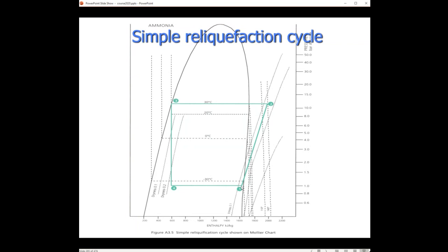Here we take away the vapors, this should be outside of that, because otherwise there is still liquid inside the vapors, and that is not so good for your compressor. So it should be outside this, on the right side of this bold line. Then we have the compression. Then we have the condenser that takes away the heat. And then we have the adiabatic expansion till here, where we have liquid again, mixed with 25% of vapors. In this case, at a temperature of -32, so this is for ammonia, as is mentioned here.